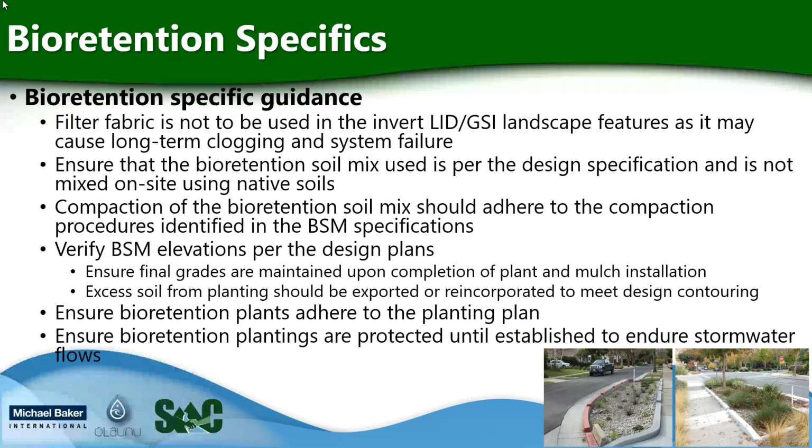Make sure that the bioretention soil mix is used per the design specifications, and we do not want to see bioretention soil mixed on site using native soils. Bioretention soil mix should be mixed off-site at specific wholesalers or locations that sell this material. Compaction of the bioretention soil mix should adhere to the compaction procedures identified in the BSM specifications.